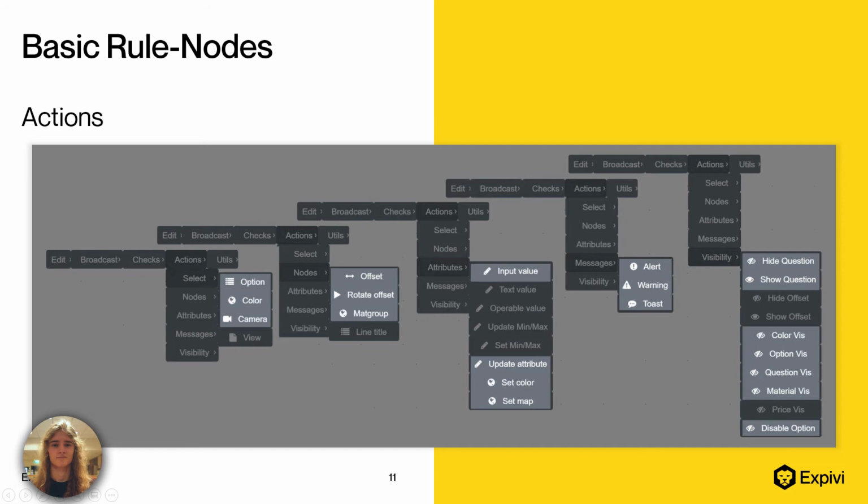If you want to translate among multiple axes independently, you will have to give each translation its own level. For example, increasing a table's width requires an offset of the legs along the x-axis. Increasing the table's depth requires an offset along the z-axis. This is done through two different offset nodes.